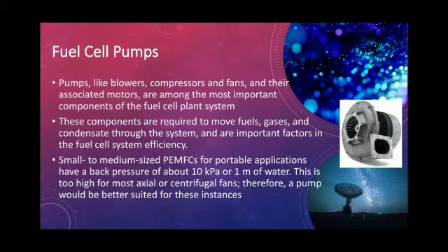Last but not least are the fuel cell pumps. Pumps, like blower or compressor and fan, are among the most important components of the fuel cell plant system. These are required to move fuel, gases and condensate through the system and are important factors in the fuel cell system efficiency. For small to medium sized PEMFCs for portable applications, there is a back pressure of about 10 kilopascal or 1 meter of water. This is too high for most axial or centrifugal fans. Therefore, a pump would be better suited for these instances.